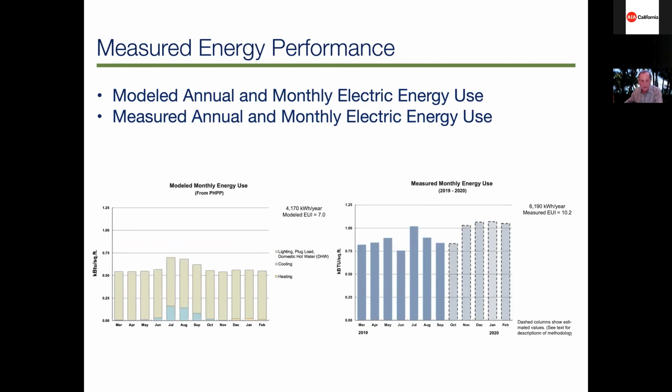And let's talk about energy performance. Again, he used the Passive House Excel spreadsheet and calculated his load to be 4,000 kilowatt hours. You can compare to the other one, which for the condo was about 5,000. So the PHPP is yielding the same number more or less. He uses 6,000. So again, we see the PHPP models a very low number, much less than actually happens.